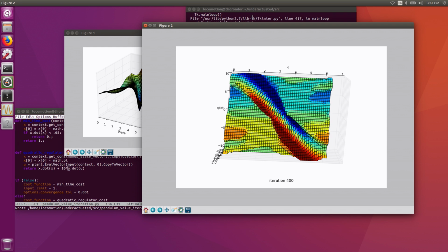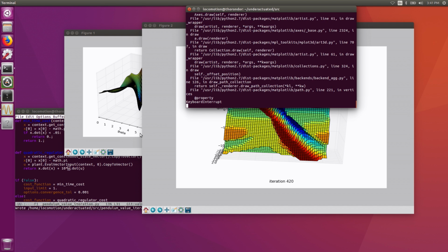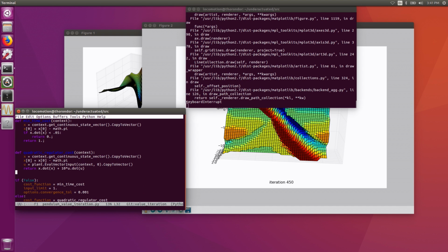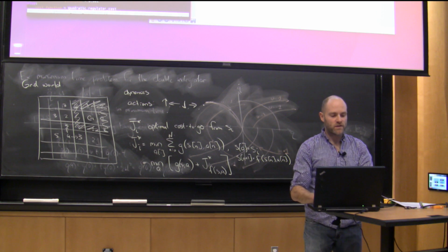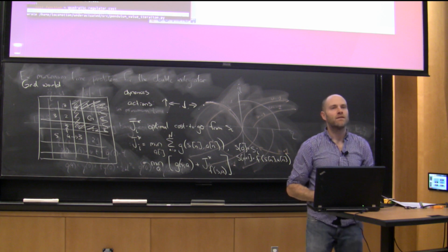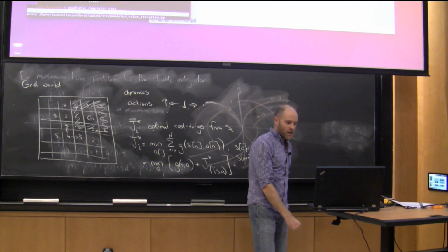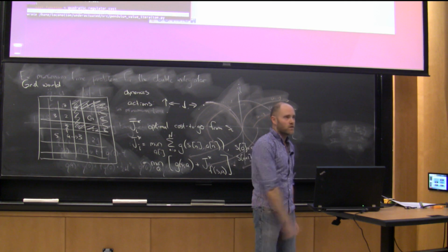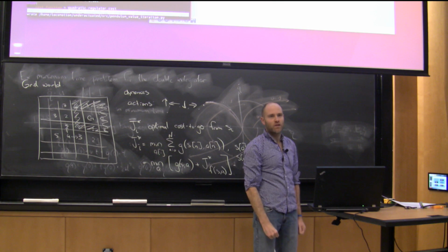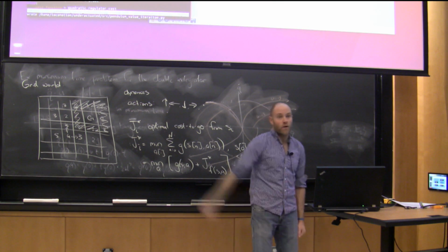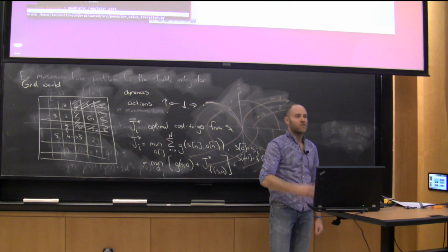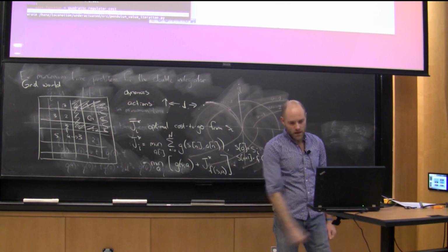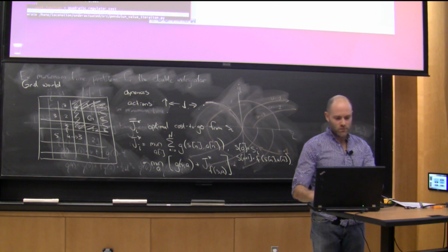Okay. What do you think the minimum time problem is going to look like? It's interesting, right? Because it depends on what the torque limits are. You can make it harder or easier. If my torque limits are very, very large, it looks like that. If my torque limits are very, very small, it could take an awful lot of pumps to get up there, right? So at some point, you're going to fight against the resolution of your discretization. I picked something in between, but hopefully with an impressive number of pumps.